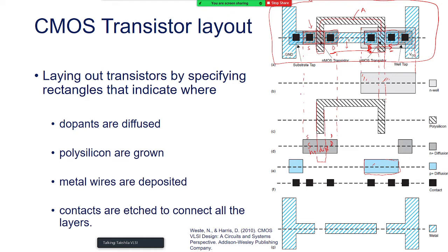So once that is done, why do I have this extra N plus diffusion region just next to this NMOS? Because this is the P diffusion region actually. Where is the P diffusion region? Let us come here. Look at this. This is the P diffusion region which is just sitting. So this is P plus. So this is the access to P substrate for the NMOS, and I want N diffusion region in the N-well also. So here, right over here.